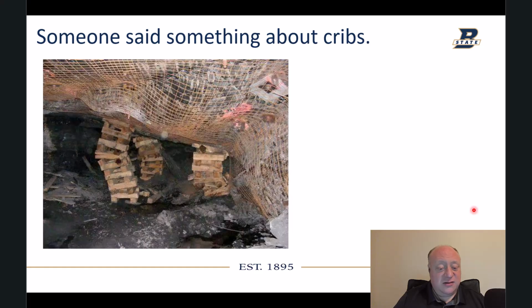And finally, someone mentioned cribs, and I found this photo, right? Back in one of the discussion questions, we were talking about supports. Someone mentioned wood cribs, and in this case, these are not 9-point cribs, they're 4s. But you can see just how much, especially this one, has converged and how much load it's taken.